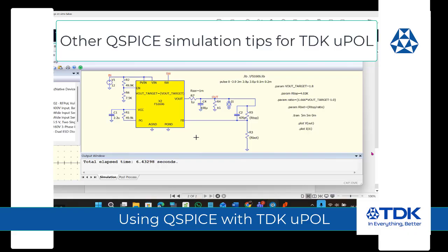This is a new program. The other thing is that the DC load doesn't really play a major role here. Now this is 100% loading, so I've made this resistor here 1 gigaohm. If you want to put a DC load, you can change this resistor to whatever you want. Just make sure you don't exceed the capability of this part, which is 6 amps.